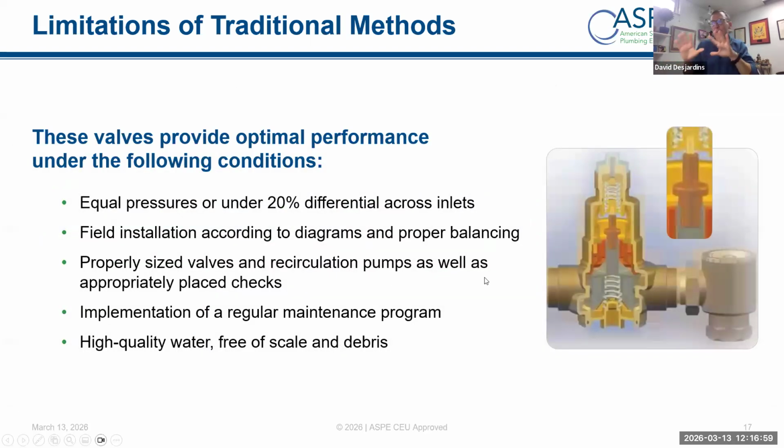When we talk about distribution, we obviously want to dial in that temperature before we send it out. So these are some rules to live by for traditional or advanced master mixing valves, per ASSE 1017. Have a pressure differential between the hot and cold within 20%. Field install these according to the manufacturer diagram. That's probably one of the things I look at a lot on mixing valves we install, and it's probably the culprit of why a lot of them are, air quote, not working. I'll talk about that briefly here.